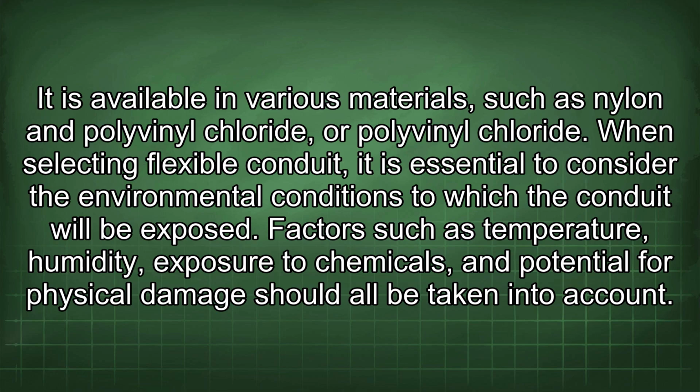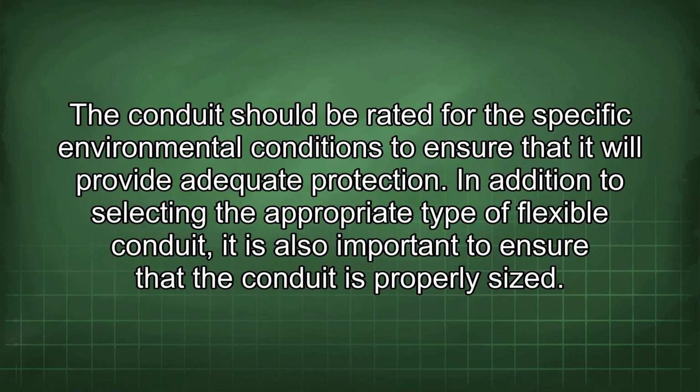When selecting flexible conduit, it is essential to consider the environmental conditions to which the conduit will be exposed. Factors such as temperature, humidity, exposure to chemicals, and potential for physical damage should all be taken into account. The conduit should be rated for the specific environmental conditions to ensure that it will provide adequate protection.